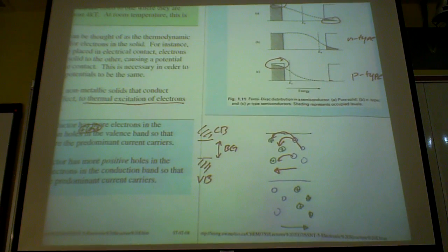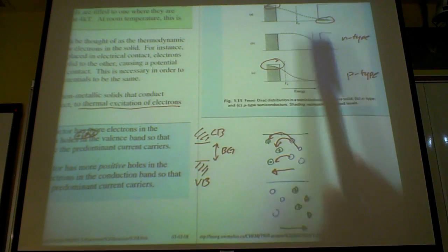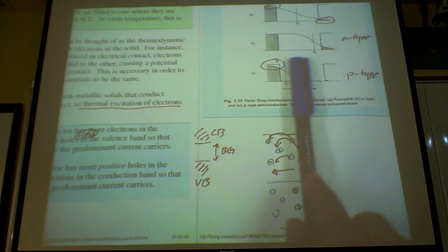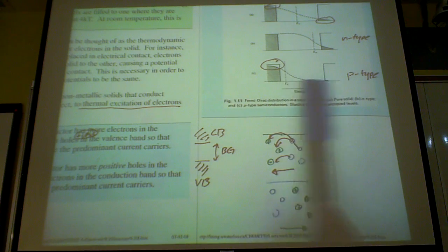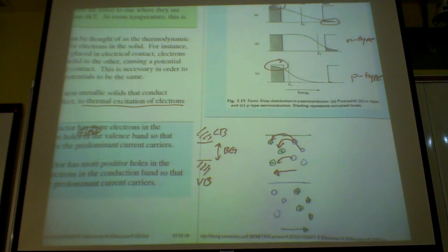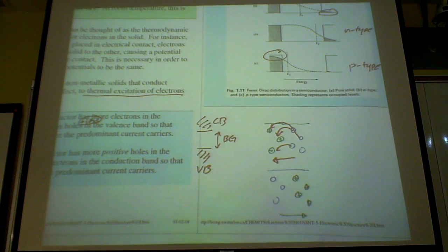So you can change this Fermi level by doping differently. You can see that Fermi energy is moving about as you dope the material differently. Okay, and sometimes this is known as band gap engineering. That is how you dope material in your semiconductor. So you can buy material with different dopant. There's a lot of industry out there that supply you with different dopant material to dope the material so that you can get the appropriate Fermi energy that you want.